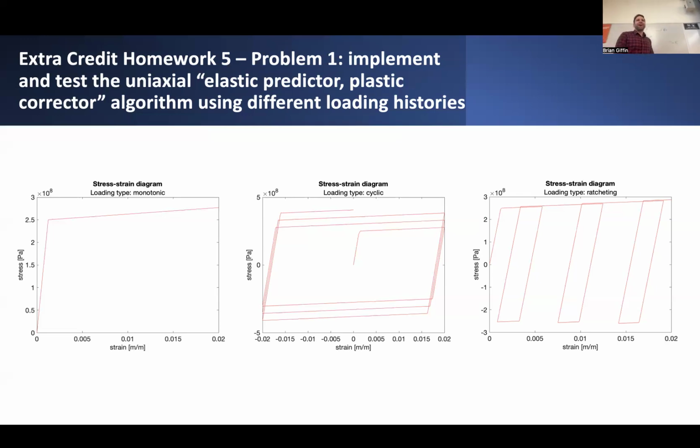Sometimes it's actually a problem in some engineering design practices, where you might exhibit ratcheting behavior in some structural component, which seems to be elongating continuously over time until eventually you get to the point where you have a component that's permanently elongated, and it's done so over multiple of these cycles. So that's a problem in some cases.